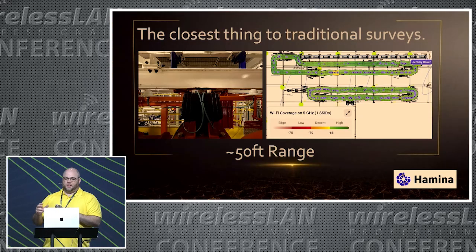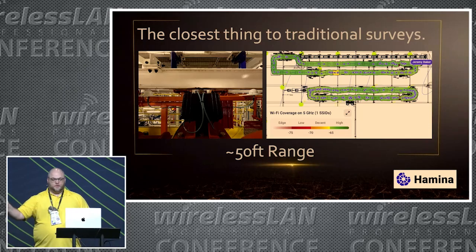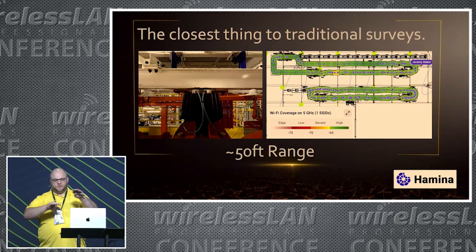So this has been kind of one of the closest things to a traditional survey tool that I've been able to do to validate these networks, aside from the areas where you can walk in there. If you look on the left, you'll see it's all kind of buttoned up, ready to go. Each of these loops represents basically 1 day of survey time. We did it as a continuous Bluetooth connection, 50, 60 feet, no problem. I surveyed for 3 or 4 hours.